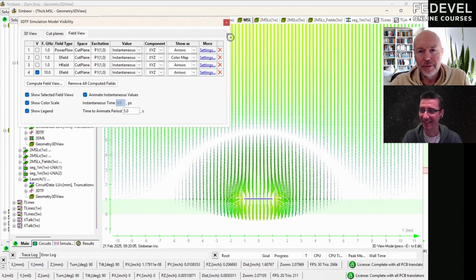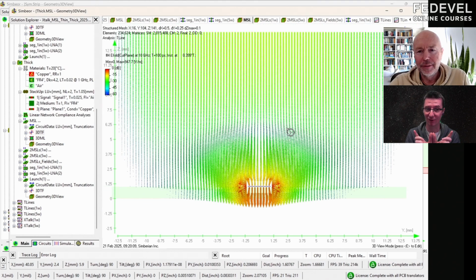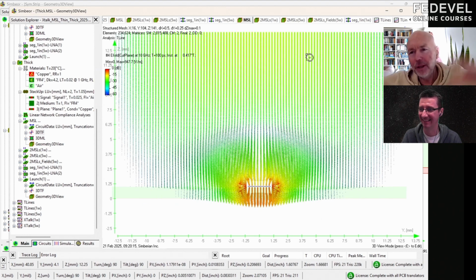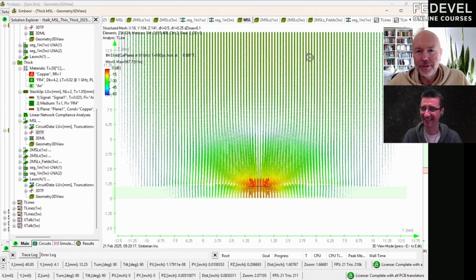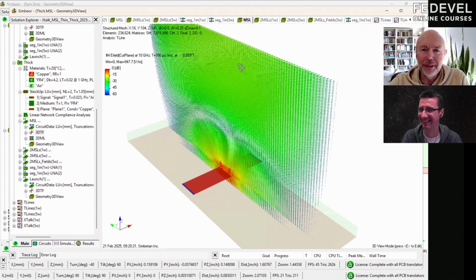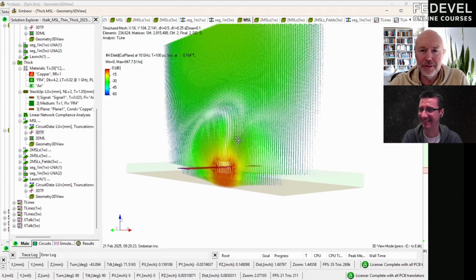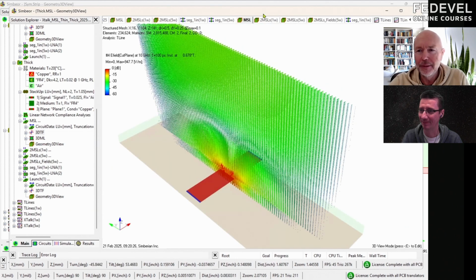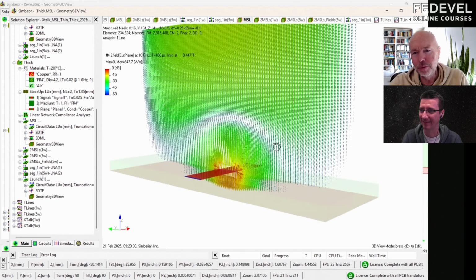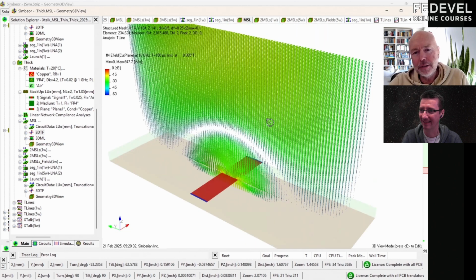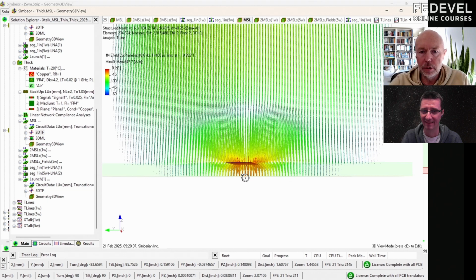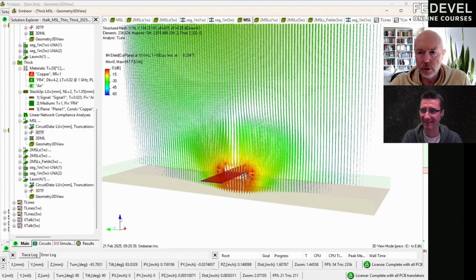Let me just close this. Okay, so the plus minus 5 millimeters was for 1 giga. Yes, it's for 1 gig. And now it radiates like this for 10 gig. And you can see the electric field over here. It characterizes the field that propagates in a completely different direction from what you want. So it's where the structure is very close to high order mode propagation, and it works like an antenna essentially on PCBs.